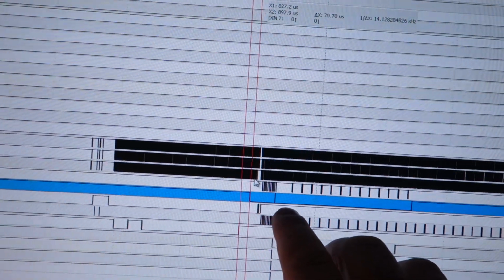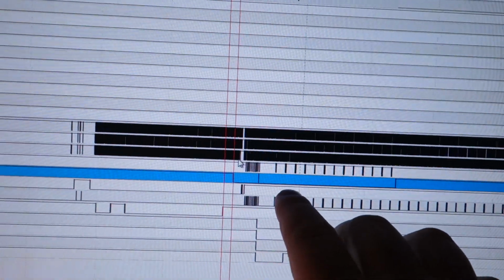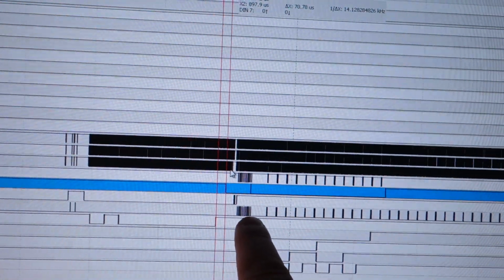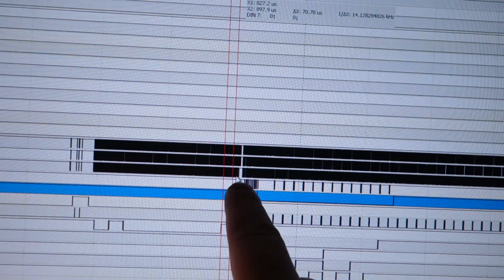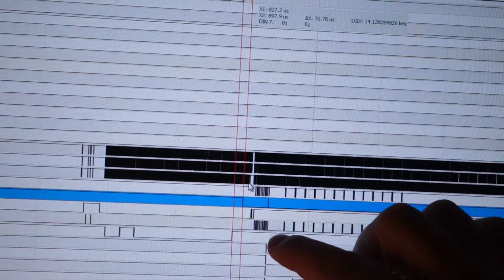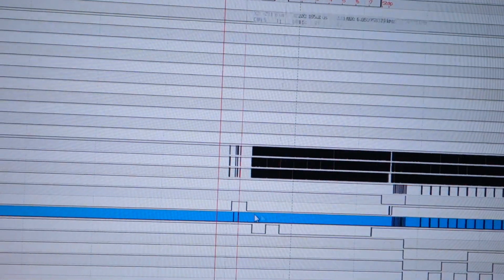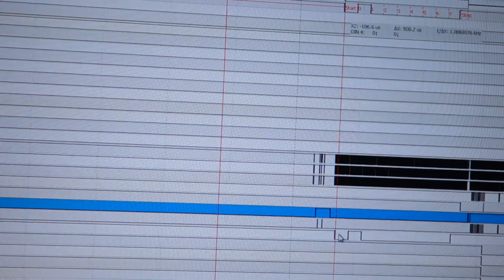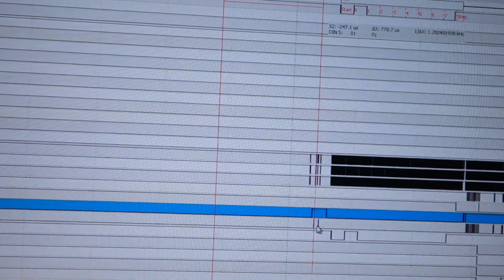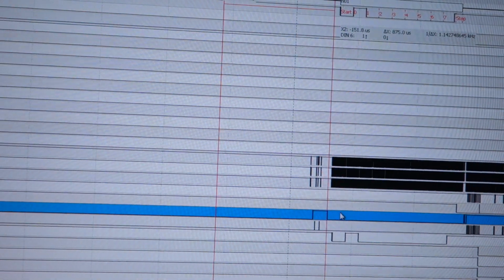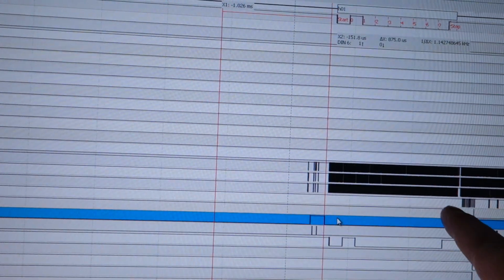Now the chip select is on our side, sort of. And we are sampling, and to get these samples out on the bus transceiver, so we can get this data out on here, we have another gate. The reason why I'm doing that is because we have some false signals, like these two would actually come through if I hadn't had this extra line coming from the Arduino.